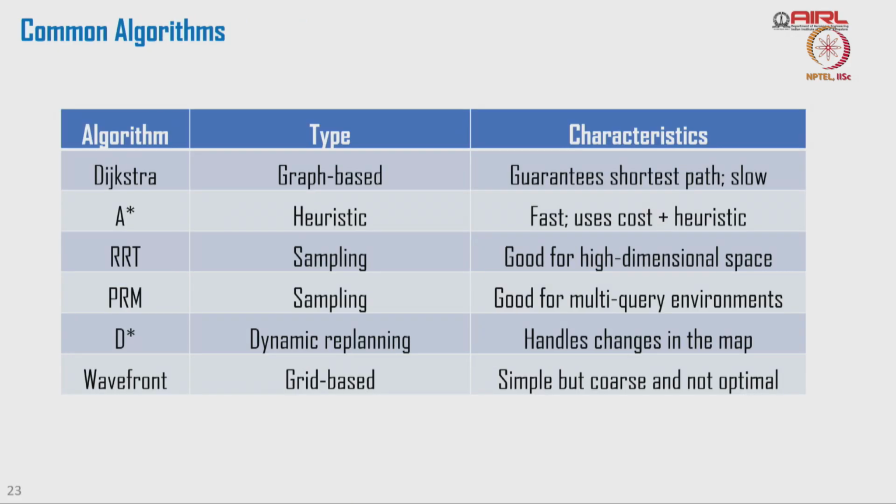Fine. So, there are some other common algorithms which are used in global path planning. Dijkstra is something we have already talked about, and based on this Dijkstra algorithm we can plan drone paths, but it has certain limitations. Then there are other algorithms like the A-star algorithm which includes a heuristic, and for that the process becomes faster. Dijkstra and A-star are both graph based search algorithms. After that we have sampling based algorithms: RRT, RRT star, PRM and D star.